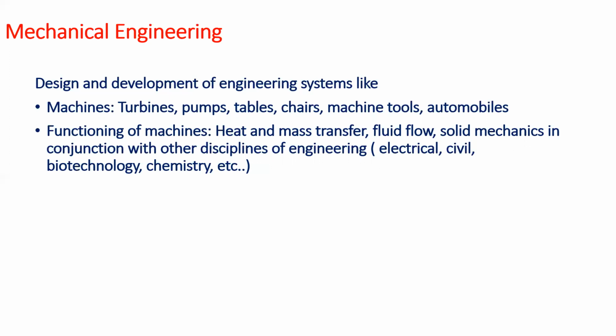And further, each of these machines has its own function. And by function, it can have various kinds of things. For example, if you consider an electric wire, when it is fabricated, it is drawn through a series of dies where there is severe plastic deformation, and eventually you get a metallic wire of desired cross section. And then a bunch of wires are stranded, and over which a particular electrical insulation coating is being laid on. Now that involves two kinds of physics.